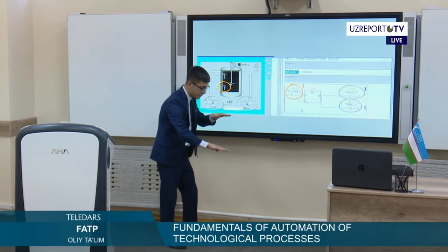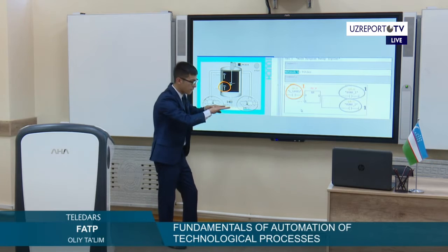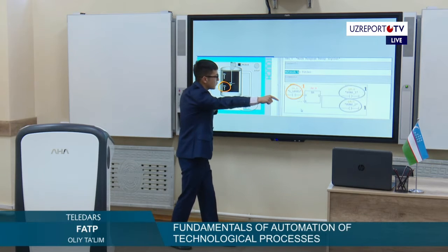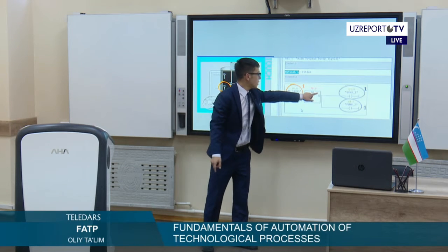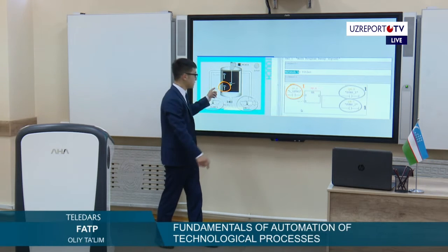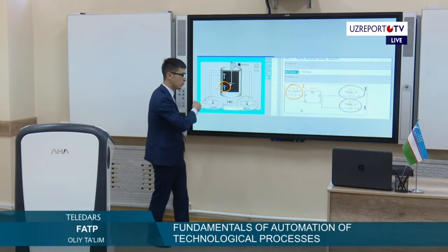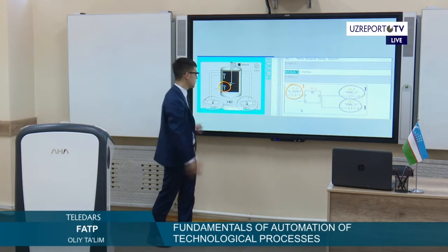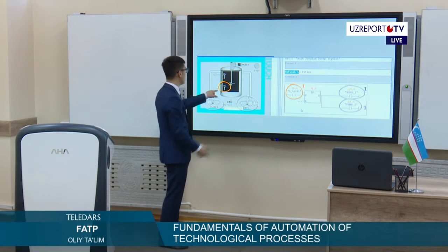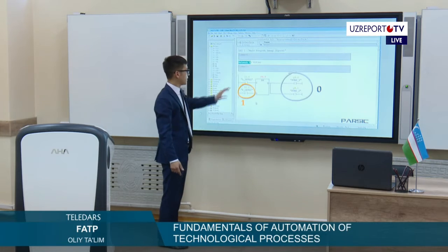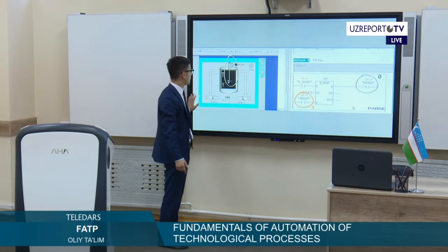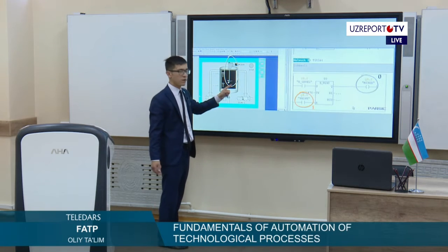It means when the sensor has a signal, it gives it to the controller, and the controller chooses to switch off pump 1 and pump 2. When the signal is over in the sensor, it means that the signal is out, and the controller makes a decision to switch on the pumps. Switch off and switch on according to the level sensor. Here we can see in the software how it looks. And next, with the mixer, how it is possible.